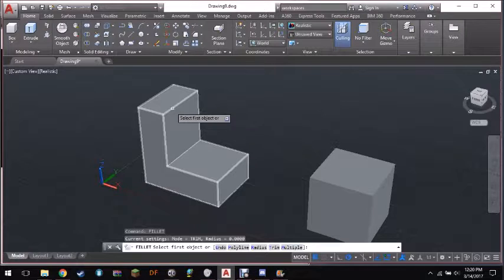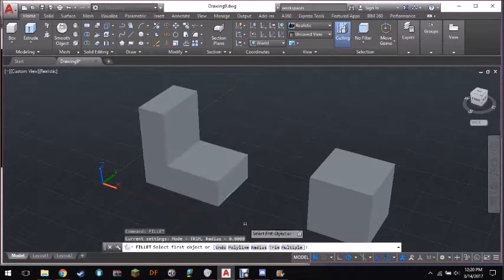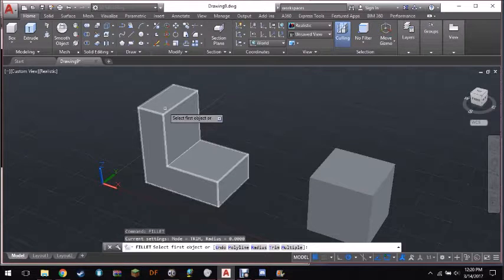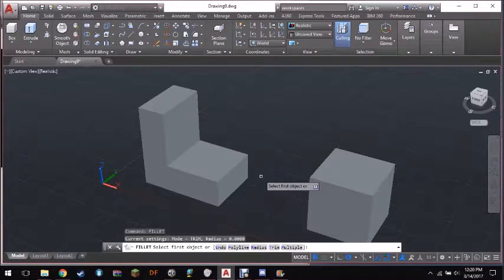Before we get to that, I'd like to talk about some of the Fillet commands. As you can see, there is U for undo, which simply undoes the last fillet that you've done. P for polyline, which in 3D has no effect because it only works on a 2D polyline. Polyline is this command here, which lets you create several lines all connected as one object, and it fillets every single joint in that line in one shot. The radius command, which in 3D I believe is redundant because it asks you to pick the radius as soon as you select the edge.